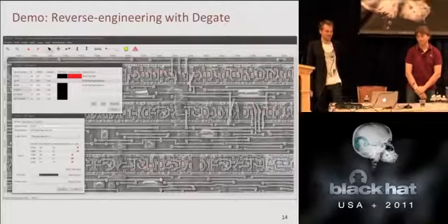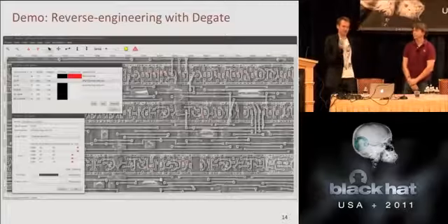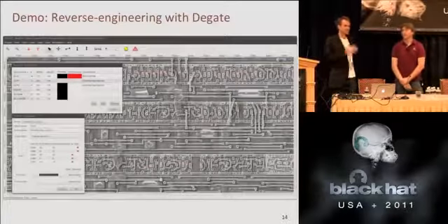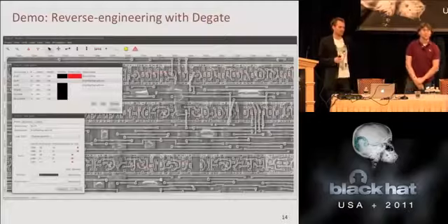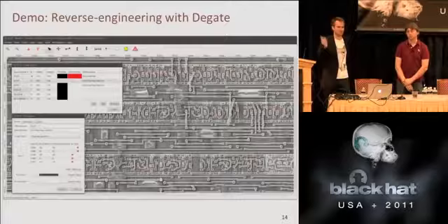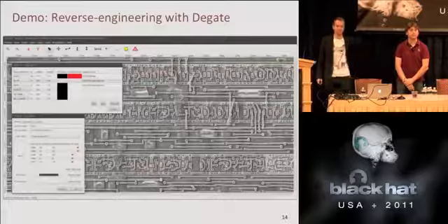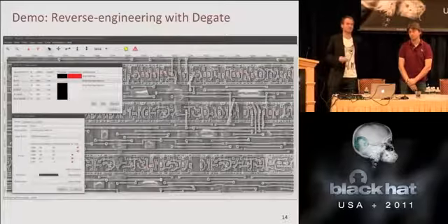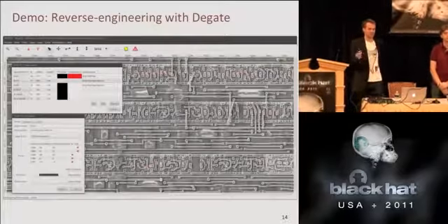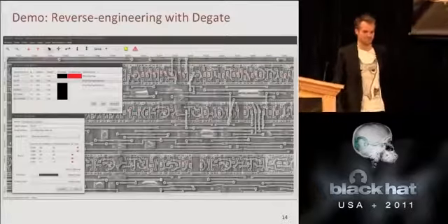But tool-wise, there's a barrier at 180 nanometer. Everything smaller than 180 requires expensive equipment to image it, and that equipment doesn't really care how small it is then. So even a 32 nanometer, the FIB or the SEM would have no problem imaging. So really 90 nanometer is already a lot more secure than something a little bigger, just because it's not optically imageable anymore.